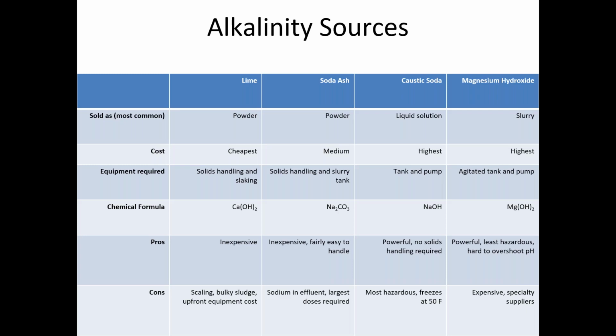The scaling issue is not insignificant. I once worked with a landfill that was having an ammonia problem, and they turned their lime dosing system up as high as it would go, and they actually scaled one of their main influent pipes shut between two of their reactors, and they had to emergency take the plant offline to clean all the lime out of the pipes.